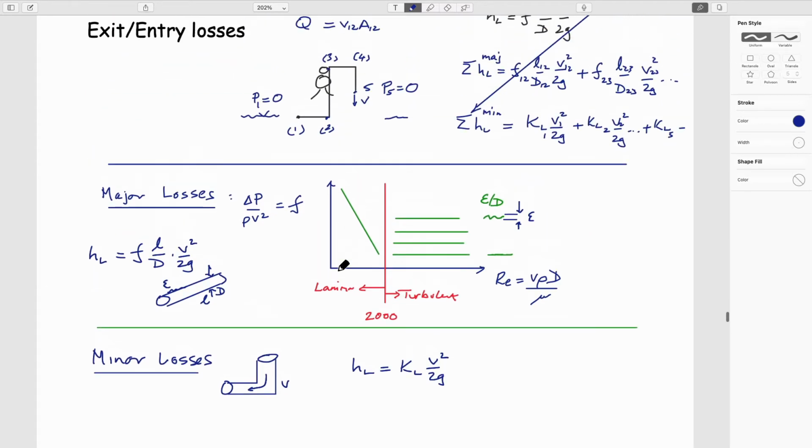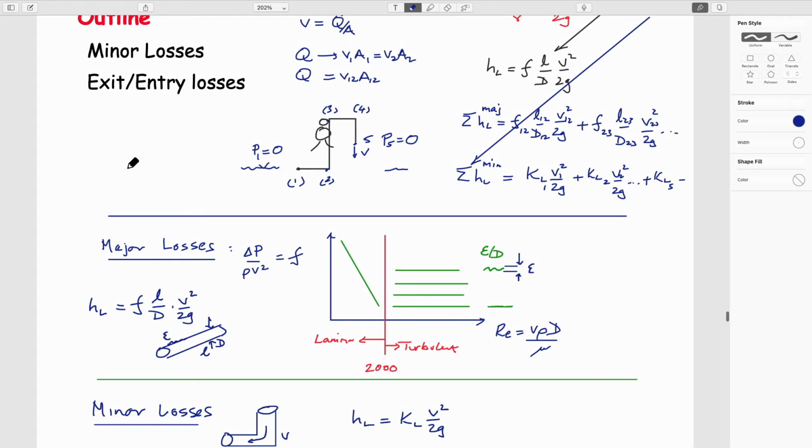And so if you happen to know the flow rate that you want in this system, so if you happen to know, for instance, what Q1 is, this would also be equal to Q5. Right? So this actually wouldn't be an arrow. By continuity, this would definitely be the case if we're not accumulating something somewhere in here.